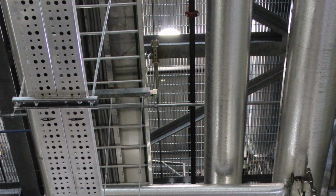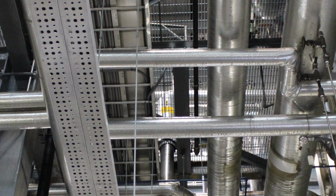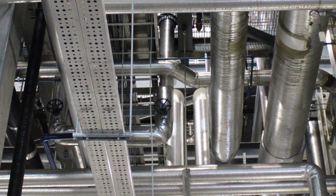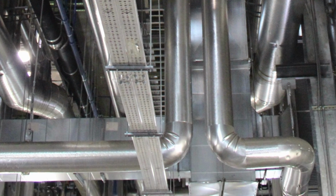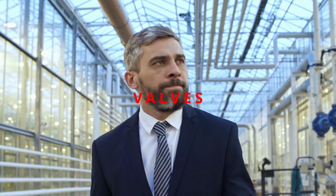This occurs along the entire length of the system and is primarily caused by the fluid's friction against the internal walls of pipes or ducts. Local losses. This type of pressure loss happens at specific points in the system, such as bends, valves, connections, and other components that cause abrupt changes in flow direction or fluid velocity.